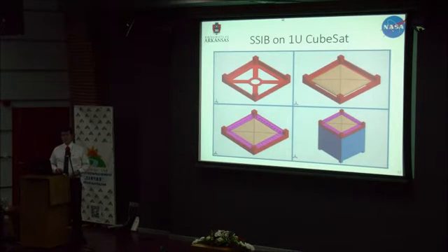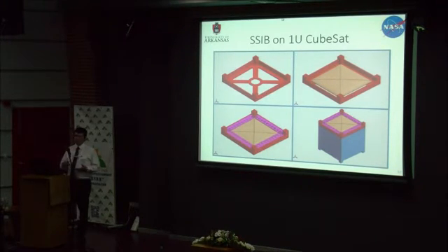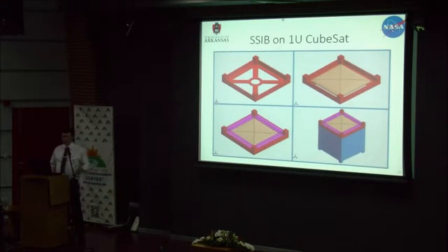One of the tricks is going to be how do we seal the balloon and evacuate it. We've looked into that. In short, what we're going to do is fold up the balloon and have basically an opening that goes to a valve. This whole setup will go into a vacuum chamber. We'll evacuate it down to 10 to the minus 7 or so torr, and then open that valve, and as the vacuum chamber loses air, the air will flow out of the balloon.